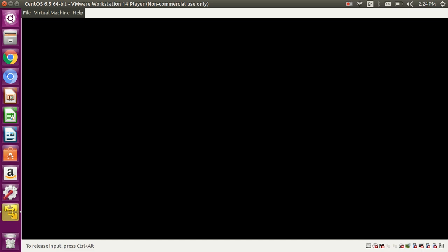In the same way, in life, or interview, or work, you just make sure what inputs you need. If that guy asks some random question, like we have an SI issue in our design, how do you fix that SI? We just need to know what the inputs are. If the SI means it is already routed, and some basic things, there is a cap difference, there is a load difference, and we have to say this is the SI. In the last project, what I have seen with SI violations is that there were tran violations because of the SI.